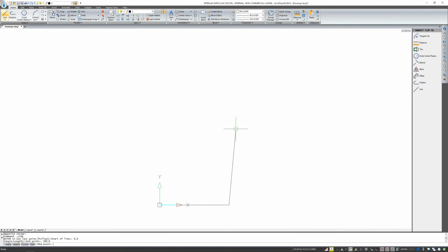Now, when I would like to go in absolute up, let's say by drawing a rectangle, then I would give it the y value, which I previously set at 200. The number of units up, let's say 500, and confirm it with enter. And I can draw a whole rectangle this way. So now there will be 0 in x, and there will be 500 in y.